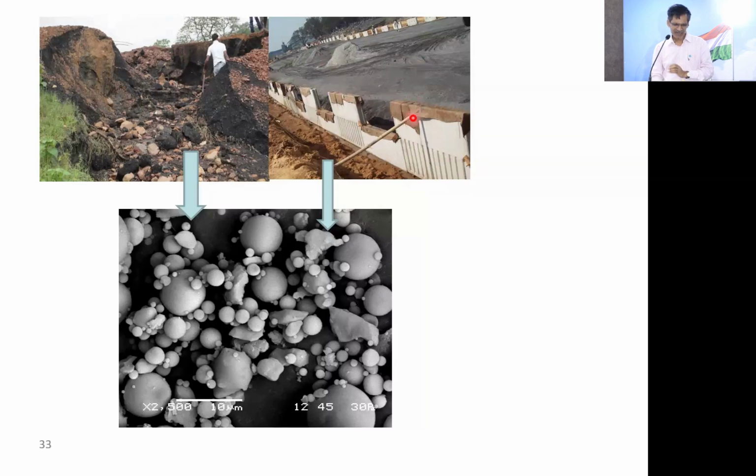So then I said, this is not acceptable. Now that we have to do all the analysis, I said, but can you tell me, with a pull out, will that strength hold? Because the fly ash when dry has almost zero cohesion. And when you are saying this friction, fly ash particles are spherical, you see, how much can they bind themselves to give this friction? So finally, when I say blending, I say that you have to add at least 25% sand.